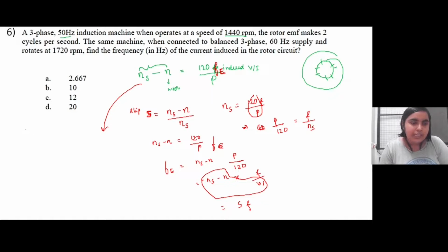So the induced EMF, the frequency of the induced current or voltage, is given as slip times the input frequency. Here this input frequency is 50 Hertz. So this is the relation that we are going to use in this problem.